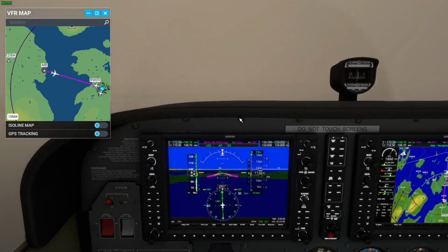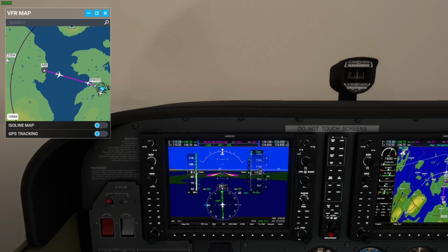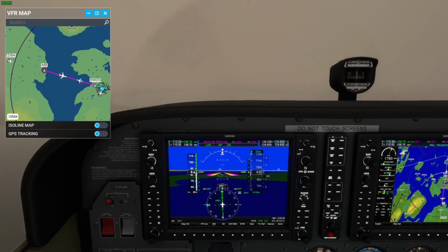Now when we're on the ILS locked in, the speed will just drop. The attitude of the plane won't change, which is not usually what happens, but the only response is the speed slows down. But that's okay. We'll keep the throttle the same and let the airspeed drop down from 90 into the 80s and eventually down into the 70s. So we're halfway across the bay,